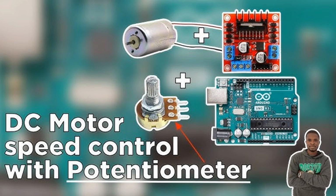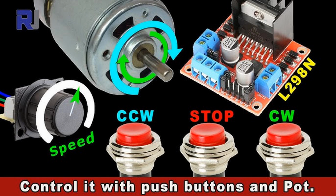Applications: Widely used in consumer electronics and robotics where reliability and simplicity are important. Summary of key DC motor driver features. Direction control, enabled by H-bridge circuits for bidirectional movement. Speed control, achieved through PWM modulation. Power handling: MOSFETs and full-bridge designs handle higher power loads. Protection: integrated circuits offer protection against potential electrical faults.